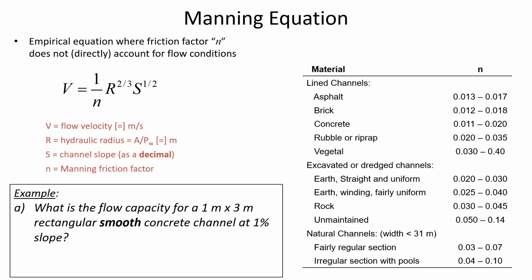That's not part of the wetted perimeter, where it's touching the air. We only want to include the location where the water's touching the resistance surface. So the wetted perimeter here is 5 meters. Why don't you pop that into Manning's equation, and let's find out what is the flow capacity, what flow rate, Q, in terms of cubic meters per second, could we expect for a 1% slope?